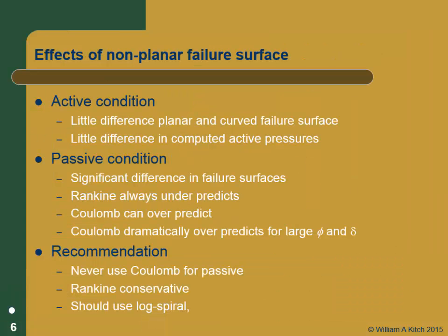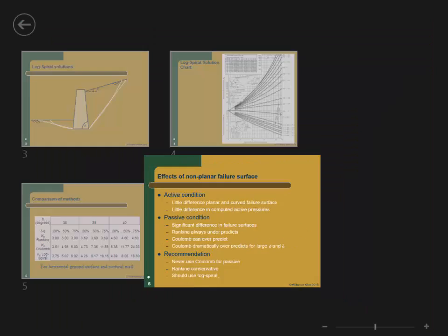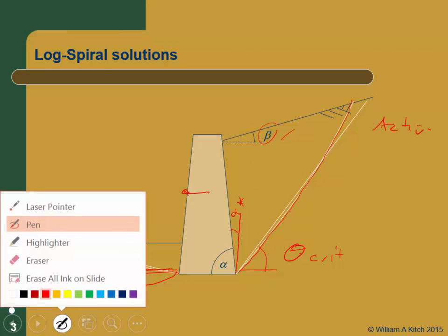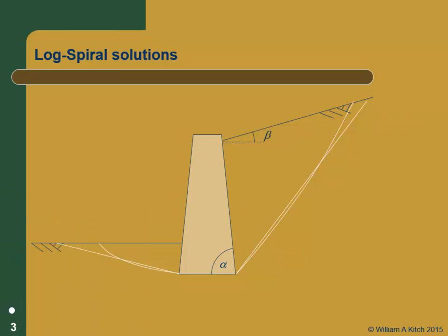Lots of times when we're using the passive earth pressure for retaining walls, all we're really concerned about is what's going on down here, and we often have a horizontal ground surface in front of the wall, even if we've got a sloping angle behind the wall. And usually for most walls that aren't gravity walls, you have a vertical face here. So it's actually a pretty good solution for a lot of your passive pressures. If you want to calculate passive earth pressures and you don't want to use the chart, there's a little tool for you.